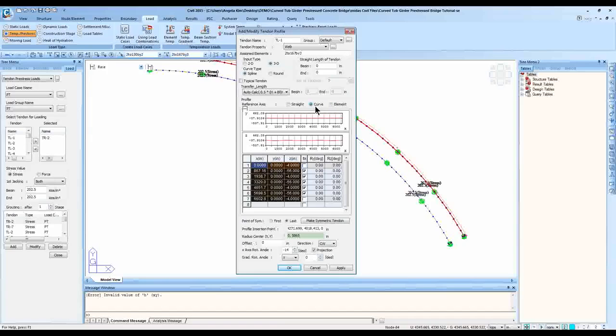So if it's very curve critical, curve may be more accurate, but based on my experiment and my clients' feedback, anyone who used it in the past, element and curve didn't really have much difference. It's actually the same for the girder too. It's a curved structure, and we modeled it with a group of straight beams. The reason why we segment it like this is to reflect the curvature properly. So same goes for the tendon. If you really need to be accurate, you can go for the curve. But from the cases, not much difference between curve and element. That was the difference between the two.